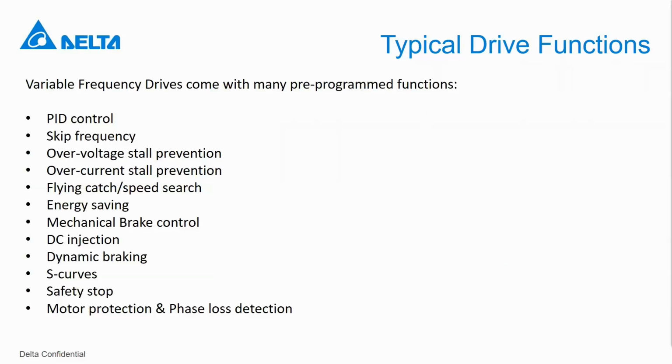There is one question still about the ramp direction. The question was: if I want a pressure of 6 bar, if below it ramps up and if above it ramps down, can I change it and operate it in another way? Normally, automatically with a PID and a pressure sensor, it will always go up and down around the 6 bar that you have as set point. Yeah, that's true. I don't quite understand the statement. Can I change it and operate it the other way?